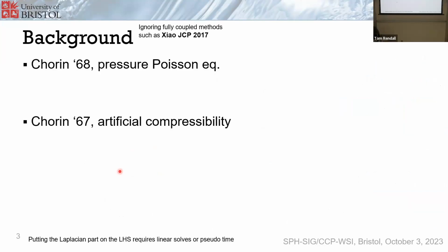So very briefly, a sort of summary of incompressible fluids, which is a challenge in a short period of time on a single slide, but we'll give it a go. Original work by Chorin looking at the splitting type approaches and similar, well, there are many variants thereof. Starting from the momentum equation, take the divergence, that gives us a Laplacian type pressure term.